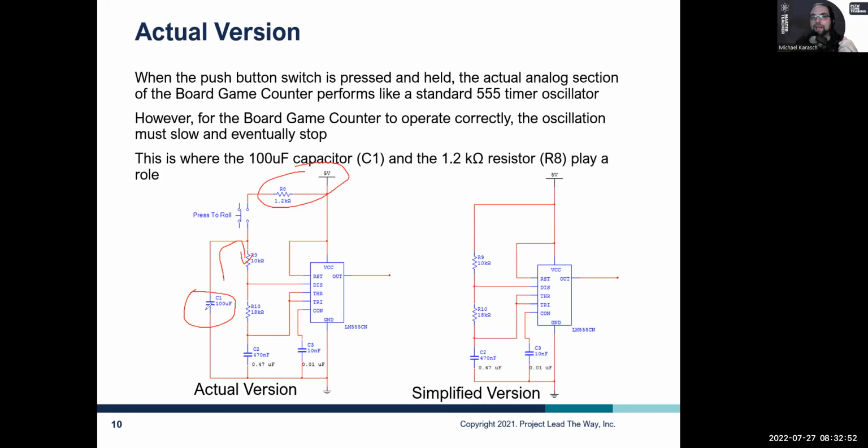So that capacitor starts running the 555 timer. It takes over. Tell the kids, it's like it's running on battery backup here. All of a sudden this capacitor takes over and it starts running the circuit. So for a moment, you don't even notice, right? The 555 timer's happily still going click, click, click at 66 hertz, right?